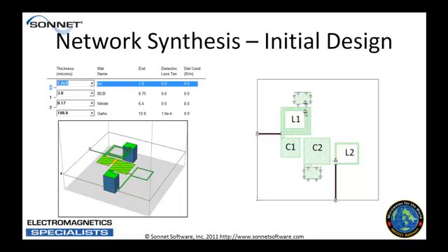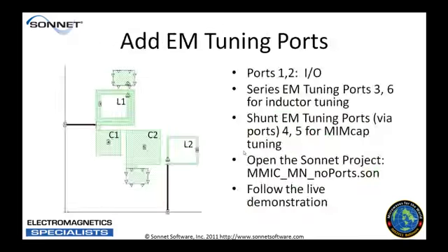Now, L1 is our shunt inductor to ground. Here's our via in this process. C1 is the series capacitor to the shunt capacitor C2 to ground. It's a via there. And then a series inductor which would go into the active device here that you can see over here at the right. So that's where we'll attach our naming convention to the parts.